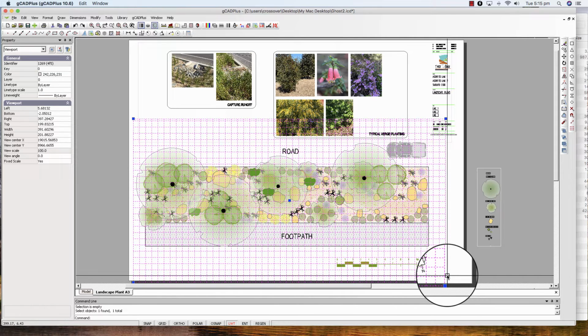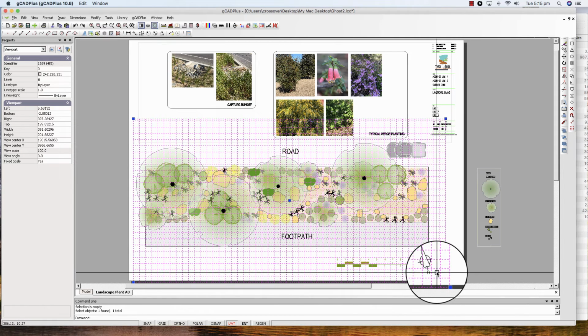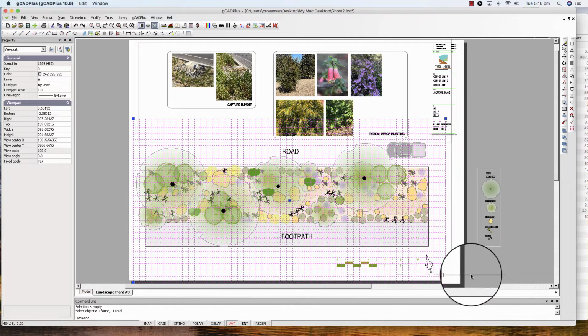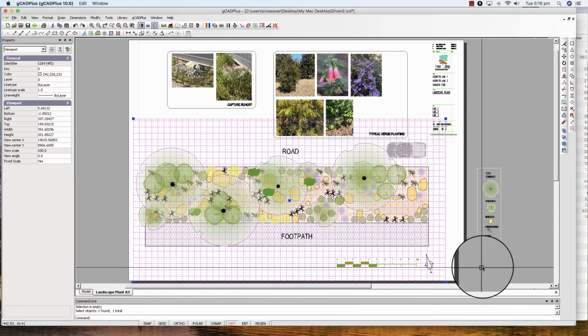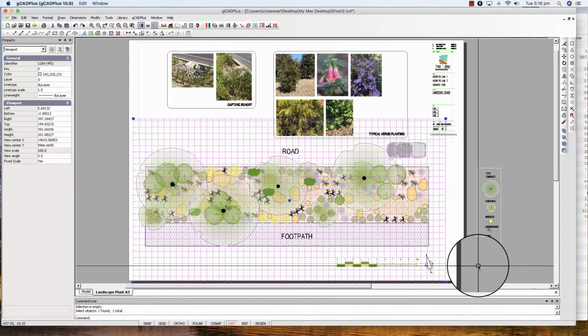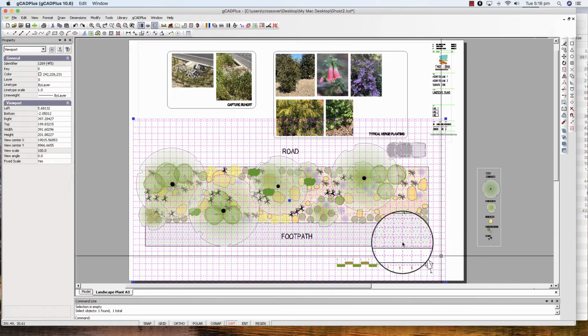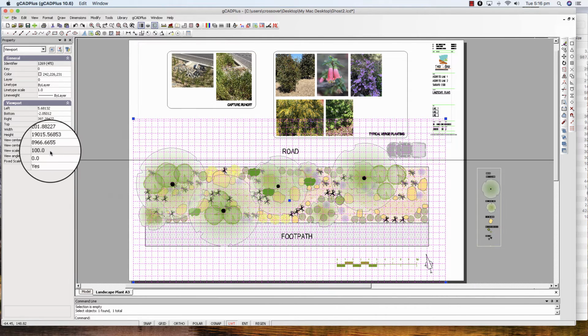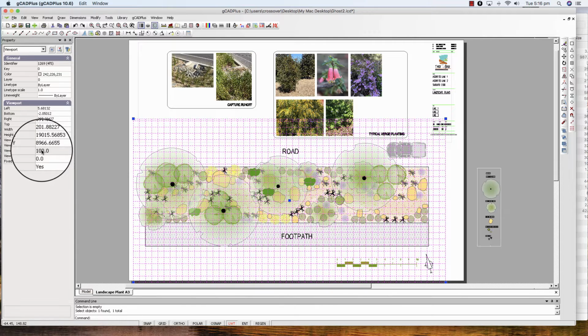I've left its colour set at 242, a pinkish colour, just so that you can see the boundary, and in a little while when we finish this we'll just set that at white so you won't actually see it. But it does enable me to demonstrate. This is a floating viewport, and if we come over here to the viewport itself, can you see there's the scale?